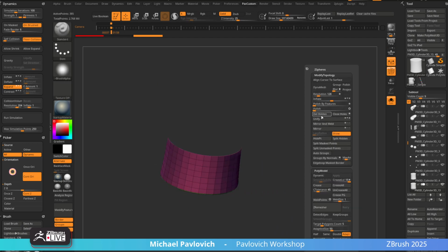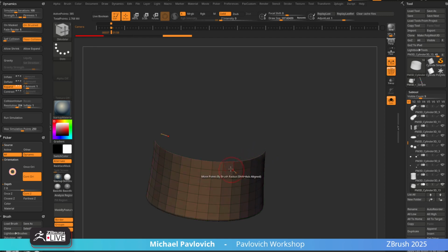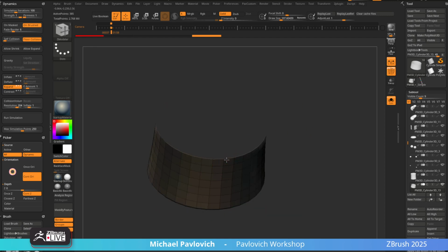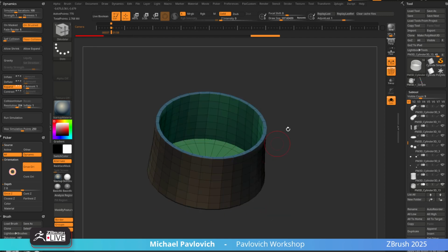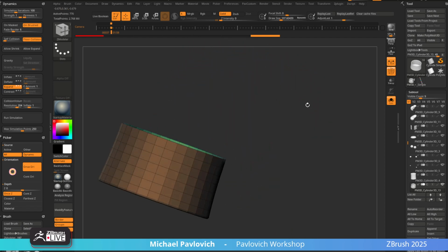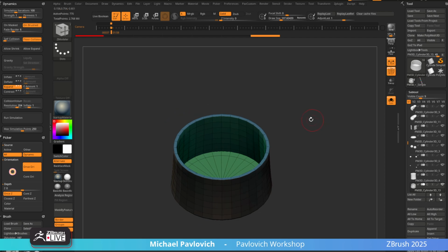Here, I'm going to say geometry, modify topology, delete hidden, Control W. I'm going to Q mesh, polygroup all inwards, and then display properties, flip. We went over that earlier. So now I've got like a little bucket that I can catch my guts in.